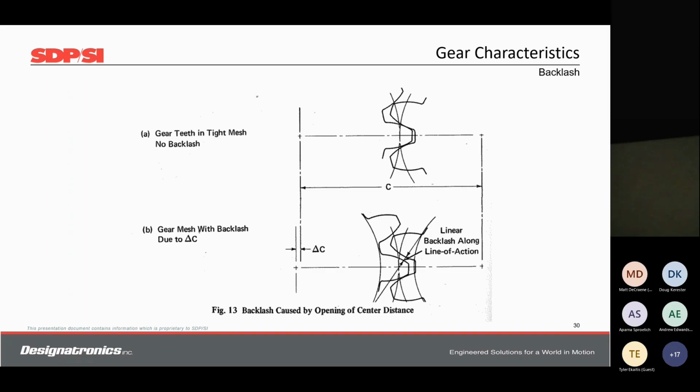So you do need a minimum backlash for sliding to occur and rotation to begin. No backlash, as you can see in the diagram above with A. No backlash means that the teeth will have nowhere to go and the forces will go into jamming the gears against each other instead of rotating. So they'll push against each other and they won't rotate. With a small amount of backlash, as in diagram B, there's space created. So when one gear turns, it will have a place to go and it'll allow for a push and the rolling action between the gear teeth, and both gears will mesh and turn.